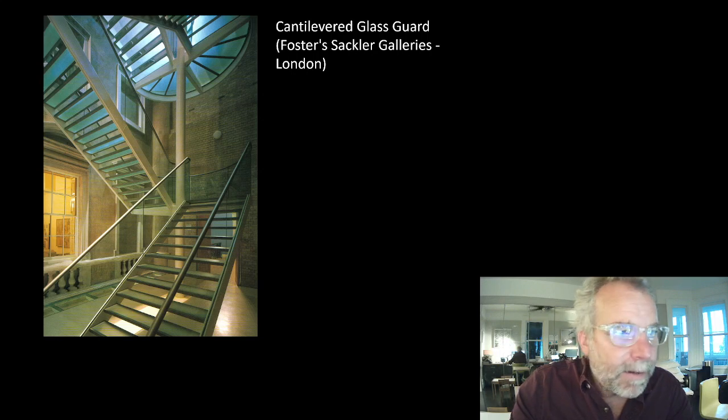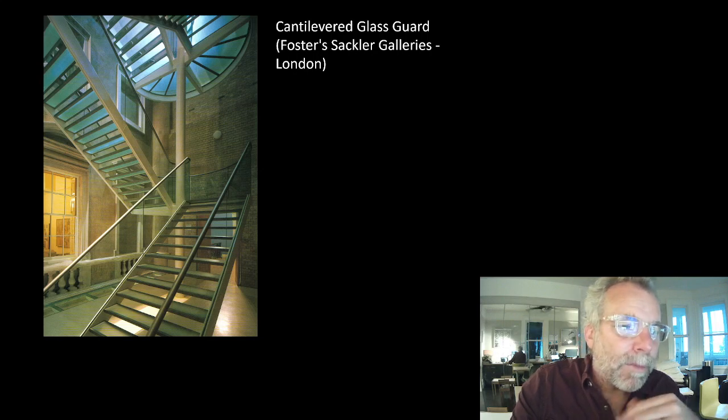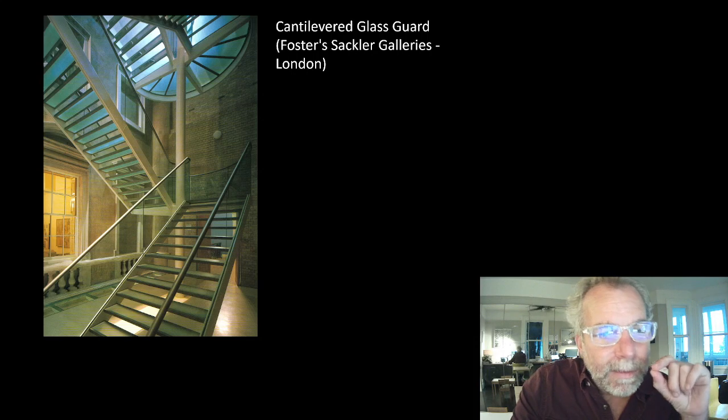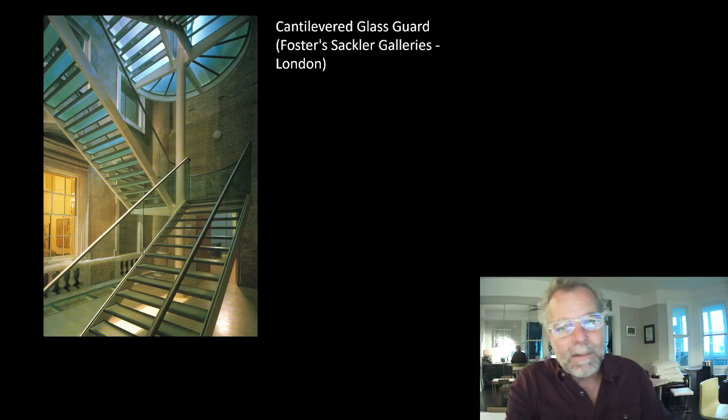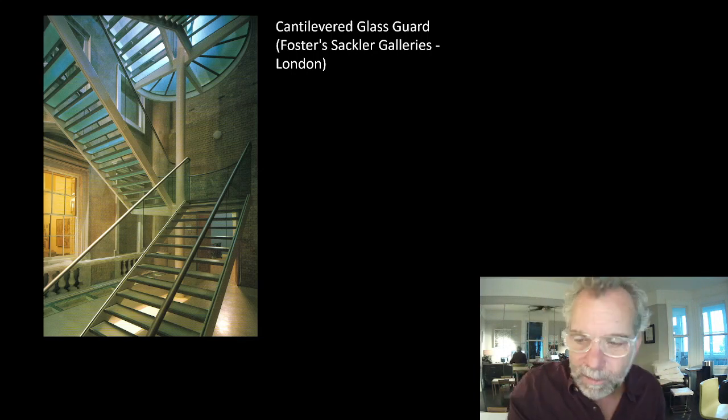So we have had difficult discussions with glass people who said, no, our glass cannot be part of the load path, and we've had to explain we're not counting on it as part of the load path. We just know it's going to damp the vibration. It's not going to reduce amplitude. It is not going to increase frequency. It is not contributing to strength. It's just absorbing energy as it slips within its shoe.